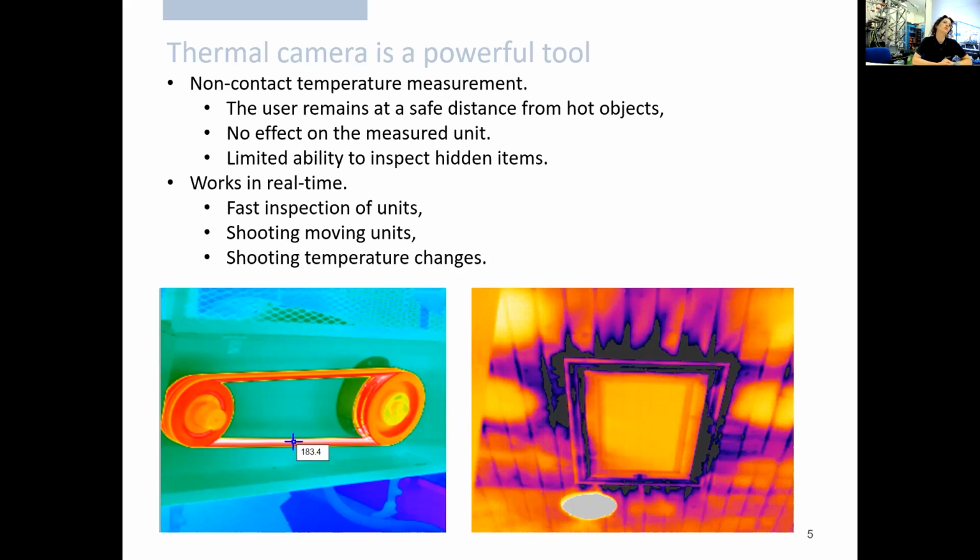Now, we can assume that we are looking at a wooden door and wooden paneling. This can be seen from the shape that we see in the scene. But why exactly we have this coldness around the trapdoor cannot be said without extra context. It could be moisture, it could be an actual spill, a water ingress, or it could be insulation that is failing.